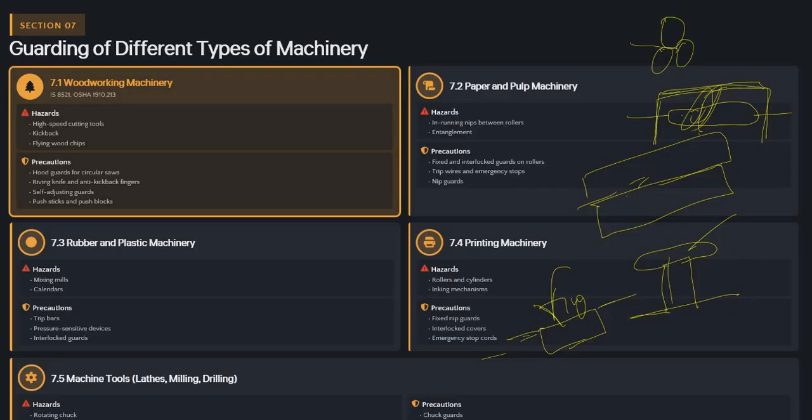So that is the reason the emergency stop is embossed outside and should be very big in size. That is the main purpose. But some industries, I see that this emergency stop also has a cover put on it. When I asked them why, they said, sir, someone on the walkway will touch it and the machine gets stopped. The purpose is that if someone is unable to reach that area, any body part that touches it will stop the machine.